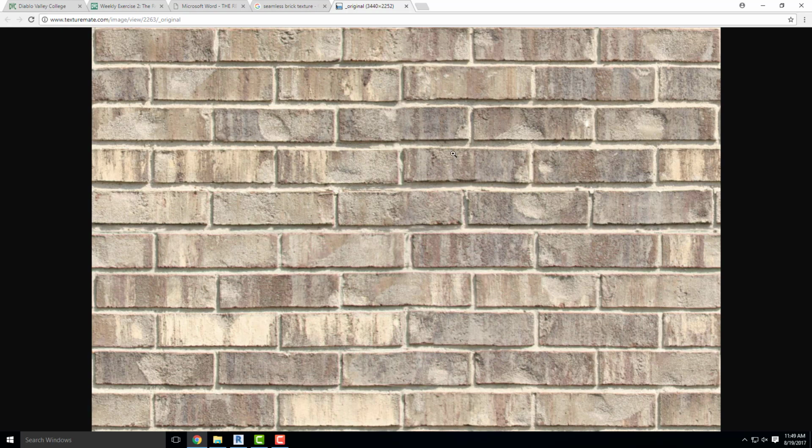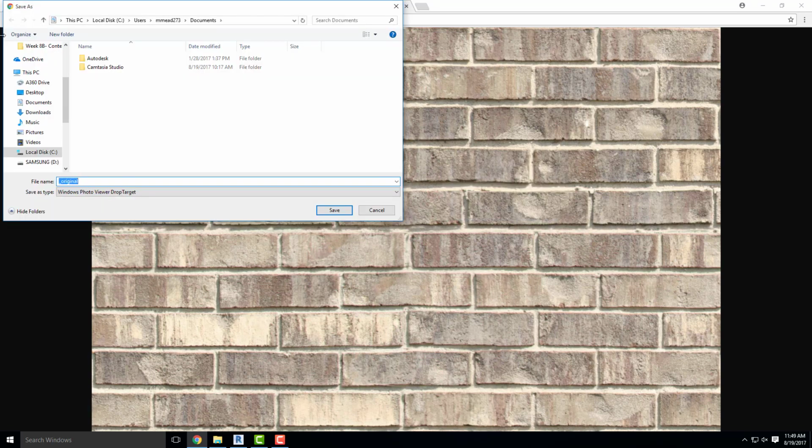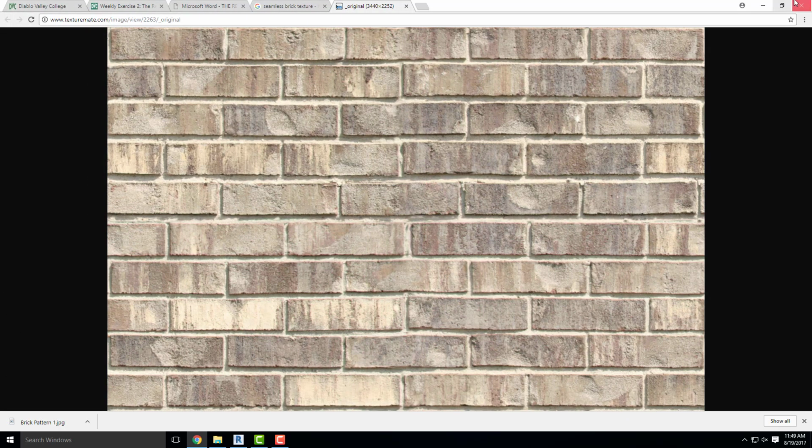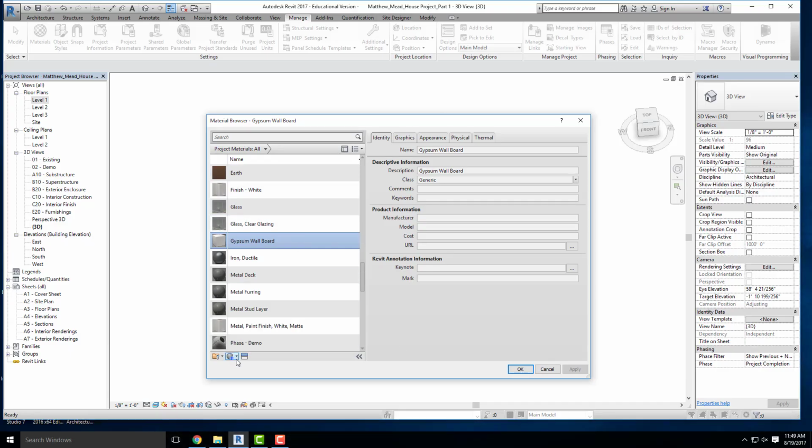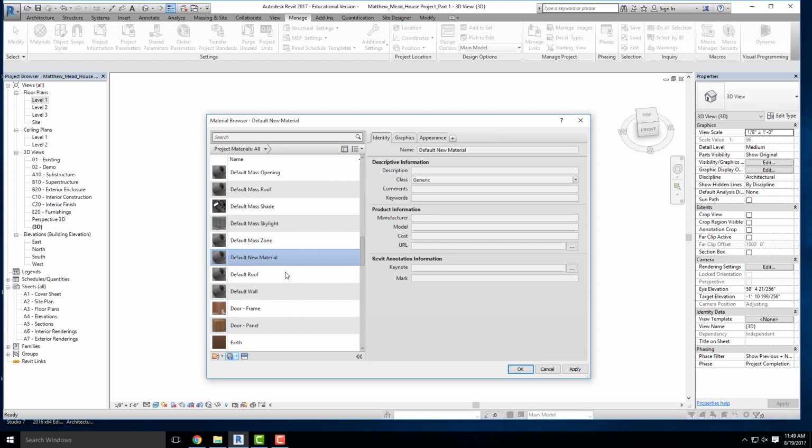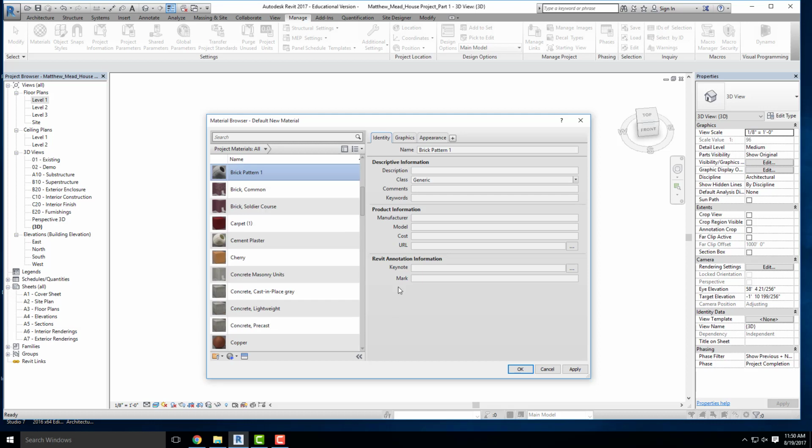Okay? So I'm going to right click. I'm going to save this image as, and ideally I would save it to my thumb drive. I already have a bunch of these on my thumb drive, so I'm not going to do that. But for the next critical thinking exercise, you'll need to do this, okay? So I'm just going to save it to my desktop for now. We'll call this brick pattern 1. Hit save, and there it is. So I've saved it to my desktop, and now I'm going to click on create new material. I'm going to rename this to brick pattern 1. All right, so brick pattern 1.